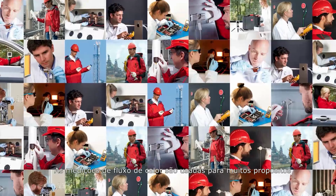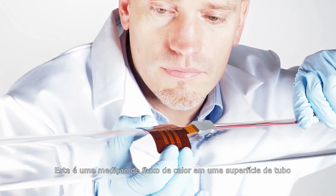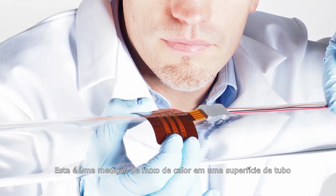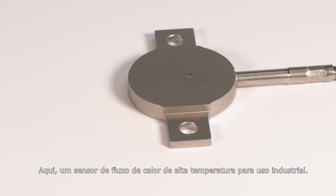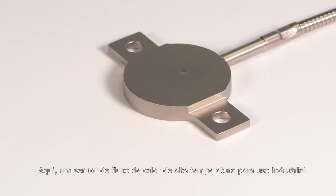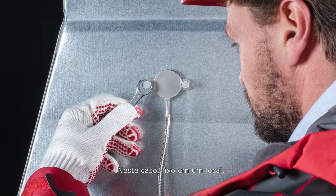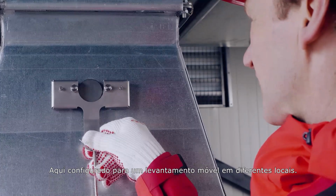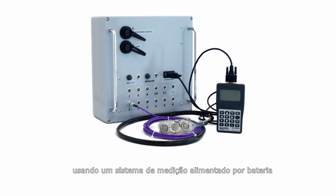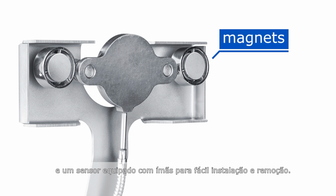Heat flux measurements are used for many purposes. Here are some examples. This is a heat flux measurement on a tube surface with a thin and flexible sensor. Here, a high-temperature heat flux sensor for industrial use, in this case fixed at one location. Here, configured for a mobile survey at different locations, using a battery-powered measuring system and a sensor equipped with magnets for easy installation and removal.